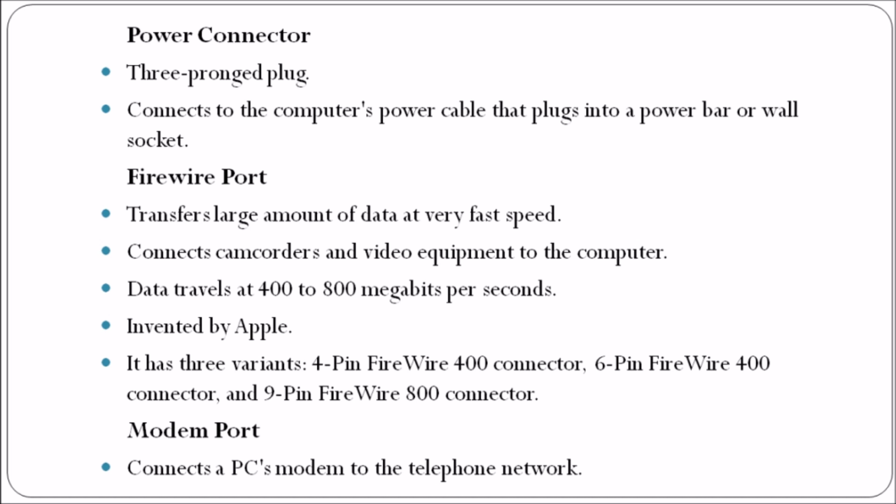Firewire port transfers large amount of data at very high speed. Connects camcorders and video equipment to the computer. Data travels at 400 to 800 megabits per second. Invented by Apple. It has three variants: 4-pin Firewire 400 connector, 6-pin Firewire 400 connector, and 9-pin Firewire 800 connector.